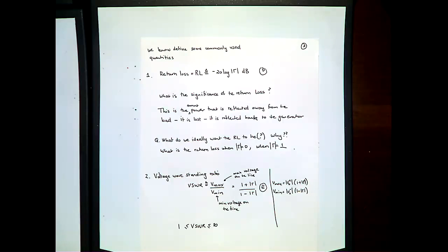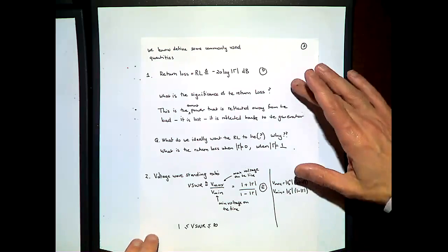So essentially what I'm saying is you put energy onto this transmission line, bang, it all comes back to you. What are a couple of examples or an example of that? Yes? When the transmission line is open circuit? Open circuit, yeah. Right, so you can have a transmission line that's open circuit, all of a sudden the power's going across the transmission line, it hits the end and can't do anything, it's open circuit. So all the power has to come back, right? Assuming that it's a lossless transmission line. Okay, perfect.